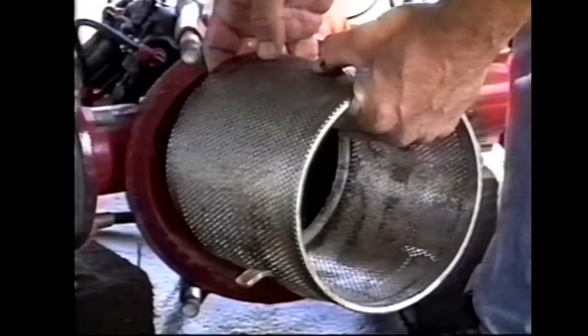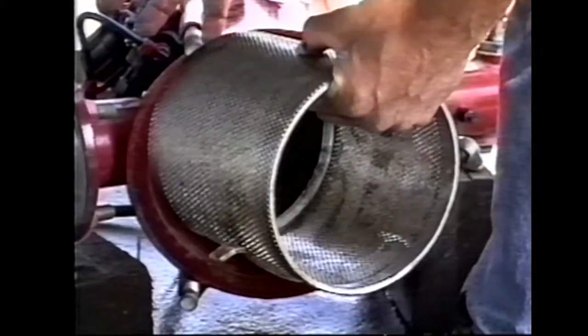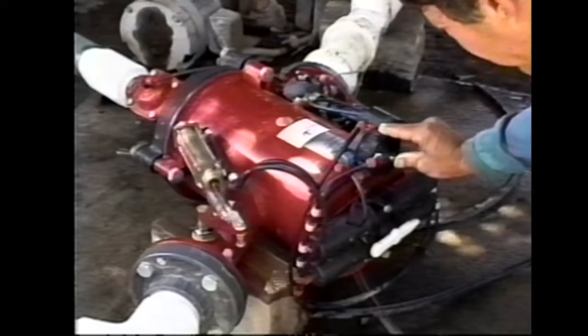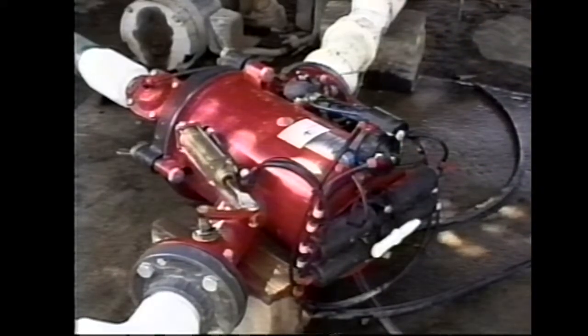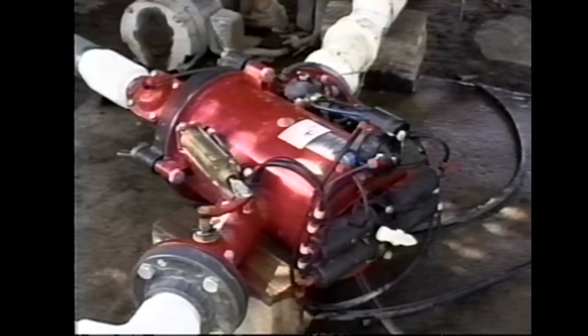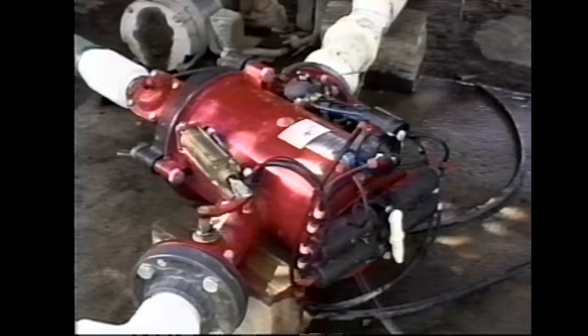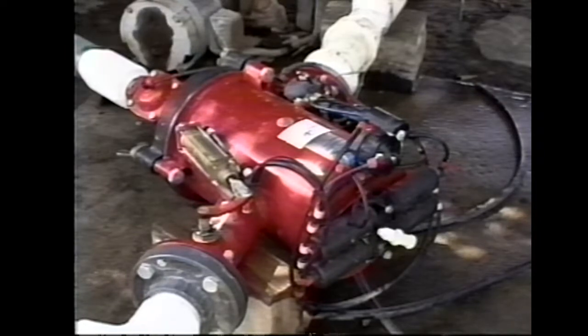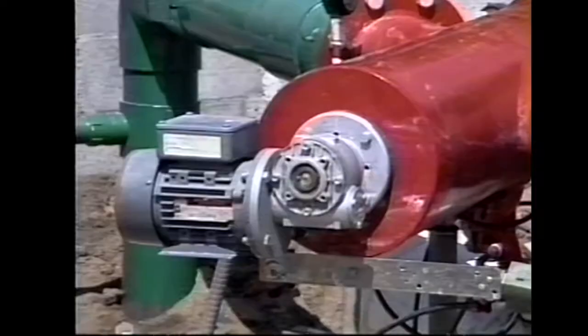The filters have a coarse pre-screen, which must be manually cleaned periodically. Here, one can see a manual activation of the backflush. The mechanism on the lower center of the screen is a pressure-sustaining valve. The white arm indicates the slow rotation of the suction scanner. Exhaust water leaves from the other side of the screen on the upper left-hand side. The whole process takes about 15 to 20 seconds.